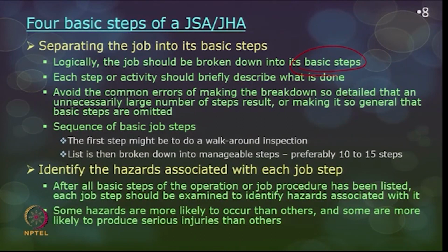The basic steps should not be omitted, but you should not have too many details. Okay, for example, loading and unloading itself, if you have almost 50 or more than 70 or 80 basic steps, obviously, if you do all the operations the same way, you may not even be able to analyze the hazards completely. Okay, so keep it as minimal as possible, but at the same time identify all the hazardous tasks, in the sense let the hazardous tasks be revealed. Okay, that you may have to keep in mind.